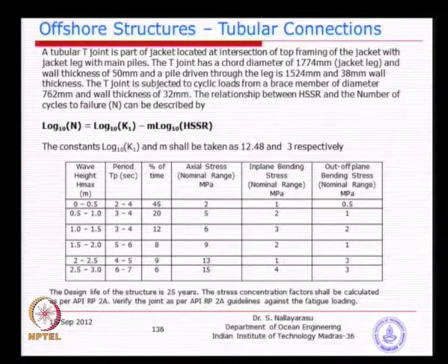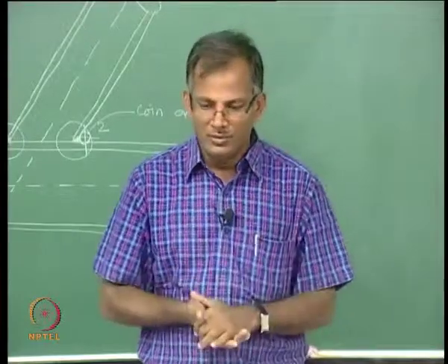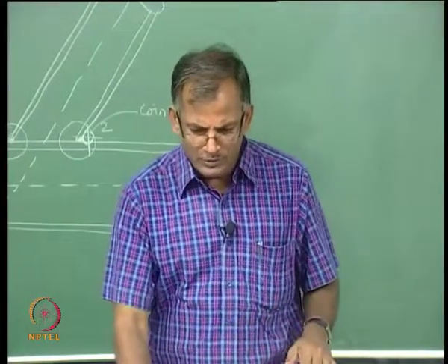Go and calculate the cycles to failure of the joint and calculate the fatigue damage for each of the sea states and cumulatively add. So, it is a very simple straightforward problem. There are no hidden issues down there. Another problem which is